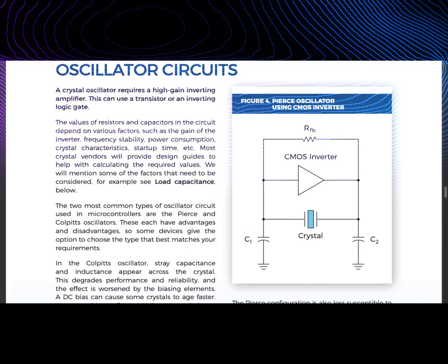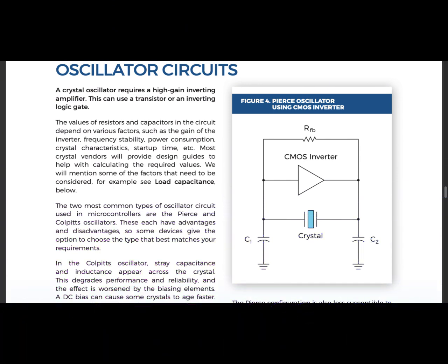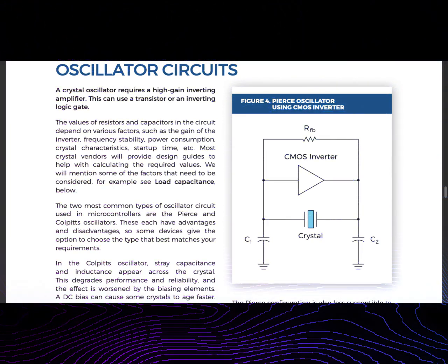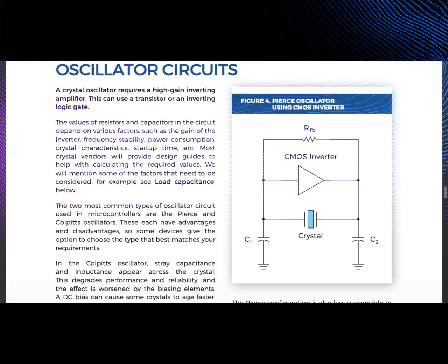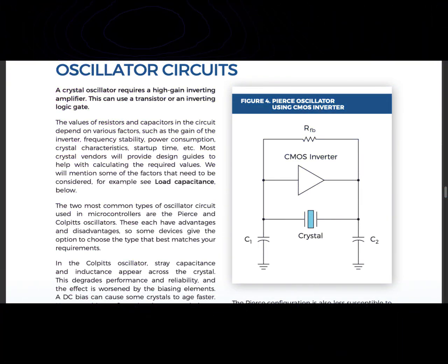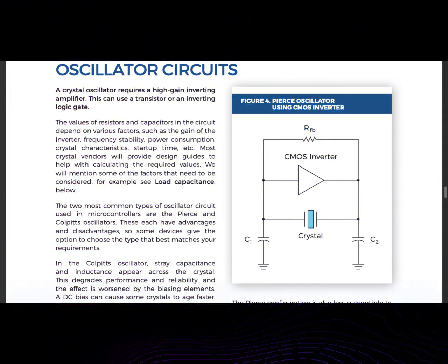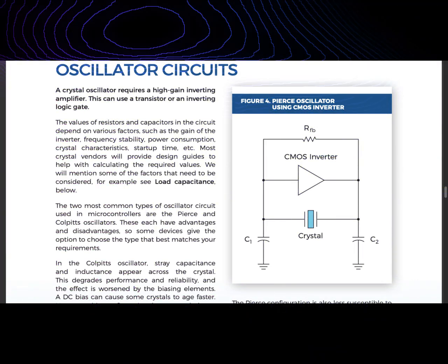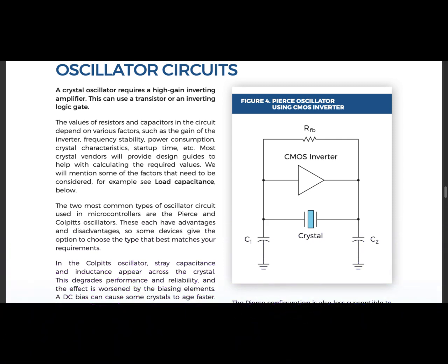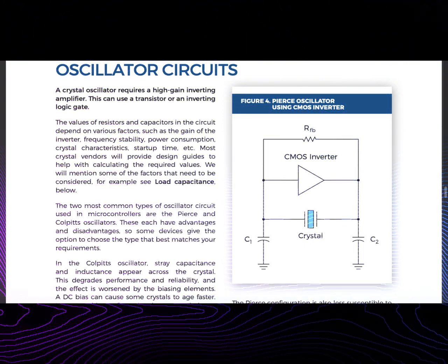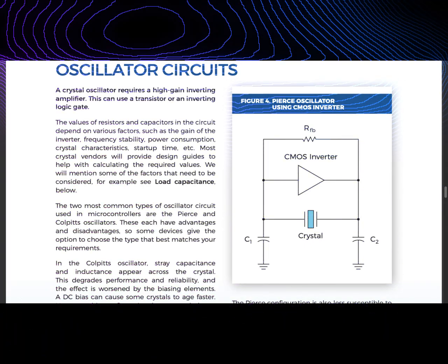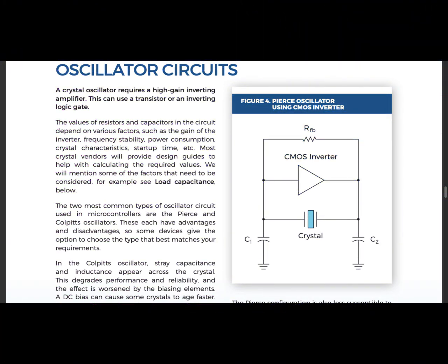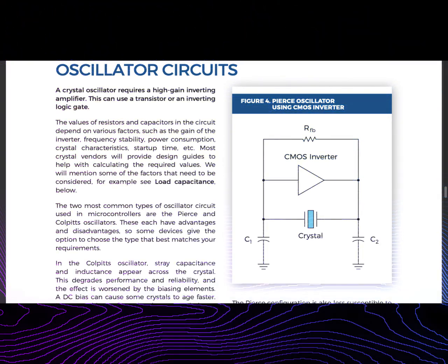The autoclave is mainly heated from the bottom, so temperatures at the top are lower. The resultant temperature gradient causes thermal convection of the alkaline solution, which dissolves the natural quartz at the bottom of the chamber and deposits it onto the seed crystals at the top.